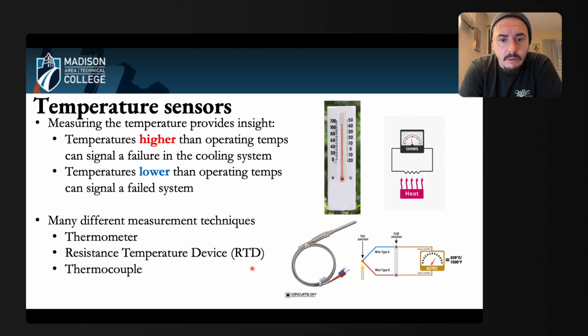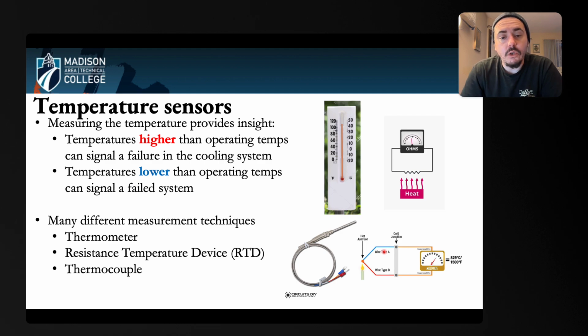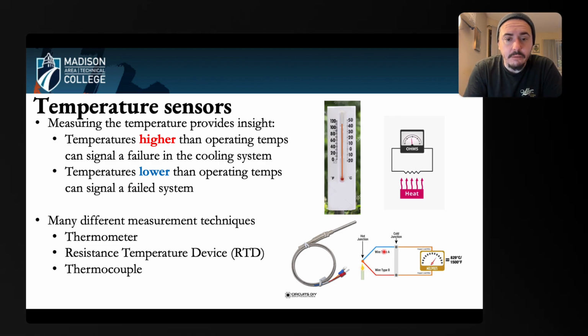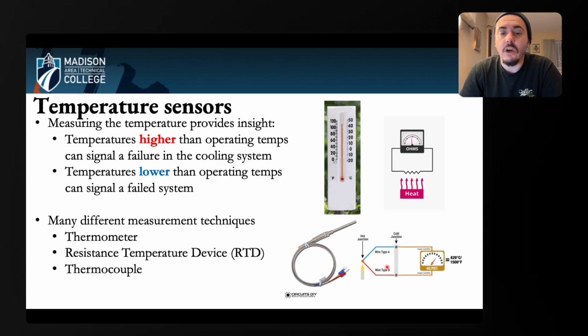There's also what's called a thermocouple. So this is something similar. A thermocouple works by, it has two separate wires, and they're made of two different materials. They're welded together at the tip here, and this is called the hot junction. And basically there's a voltage drop across this connection here, and the voltage drop across that connection is associated with the temperature. So it changes with temperature. And so these are also calibrated. These RTDs and these thermocouples typically can be calibrated from the manufacturer. They can also be calibrated in-house using like a water bath or something with a known temperature.